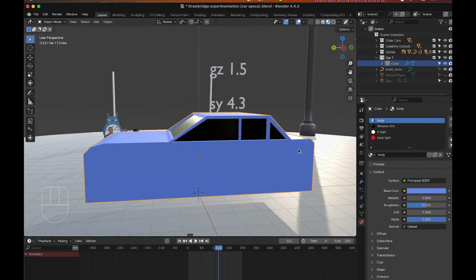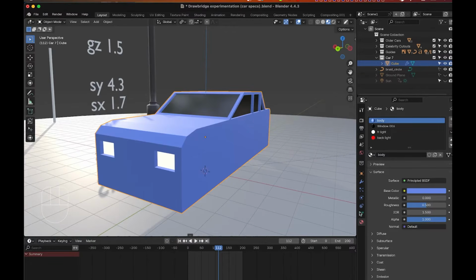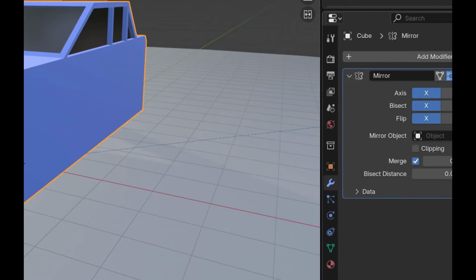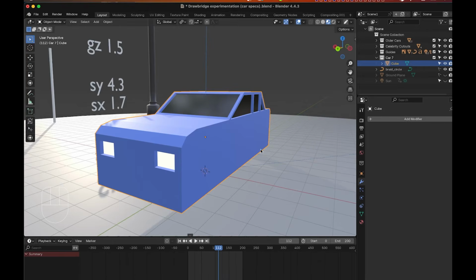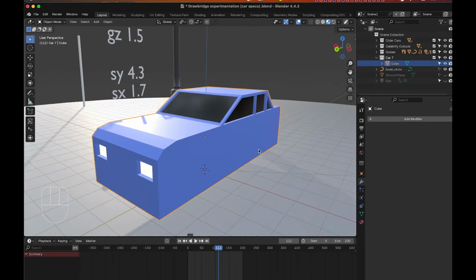We're not going to have to do any more mirroring to this particular object. So with your object selected, we'll go back to our modifiers and apply the modifier to make it permanent, okay? We've done our mirroring, all that stuff. Click this thing to the right of it, it'll drop down next to the mirror, and click apply. Okay, so now this stuff's permanent. Stuff on that side we permanently mirrored it.